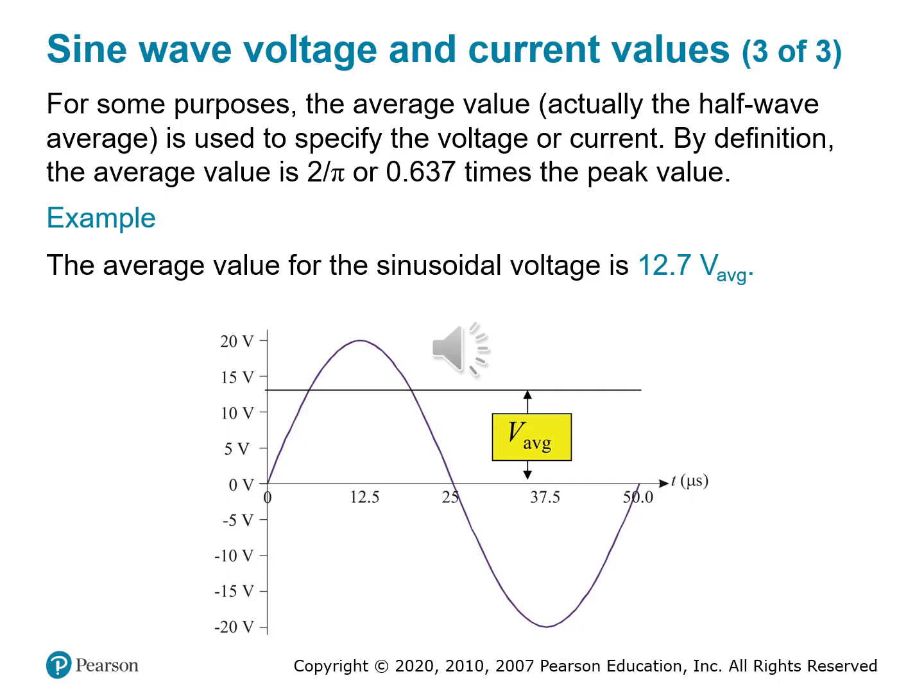This number is useful for things like rectified signals, like in power amplifiers after a diode, analog meter readings, and when designing filters that respond to signal averages rather than RMS power. And just keep in mind that V sub P gives you maximum voltage, V sub RMS gives you the heating electrical power equivalence, and V sub average gives you a measure of the effective swing in just the positive direction.